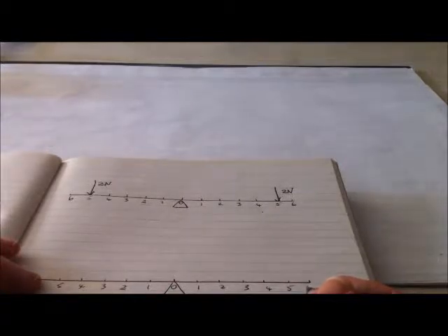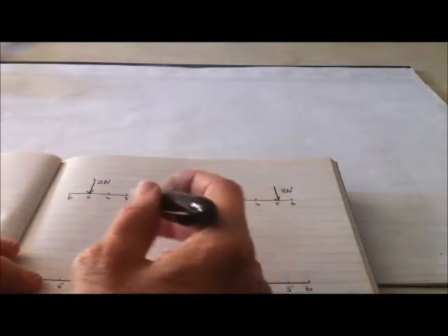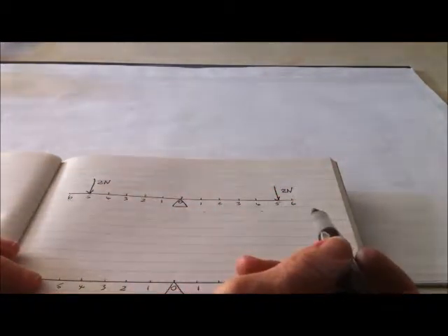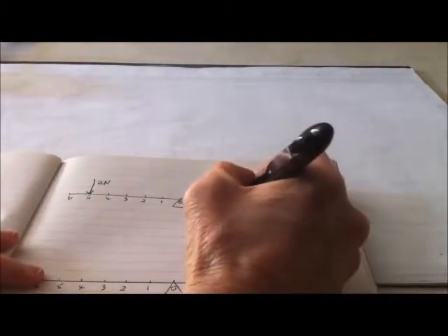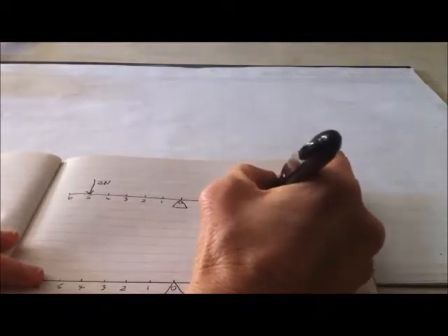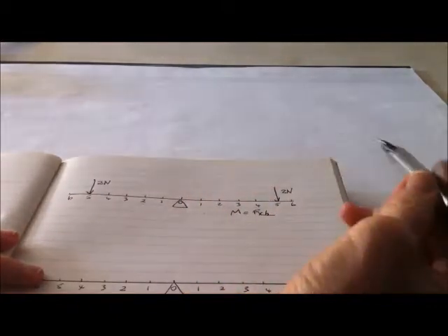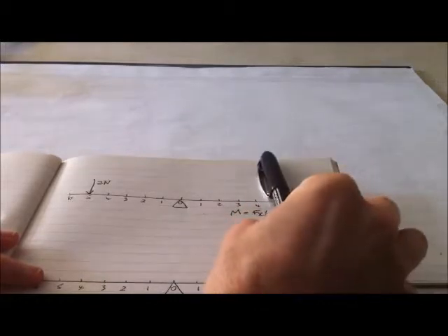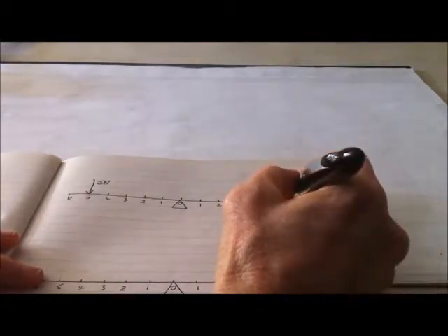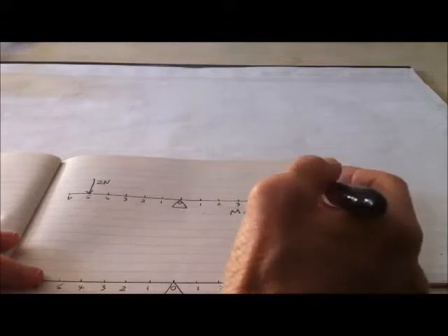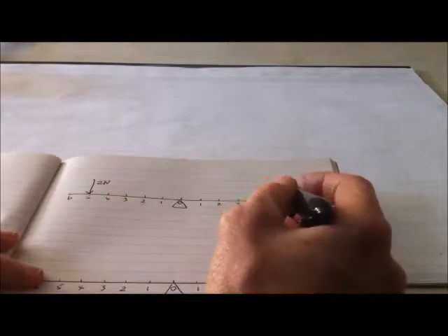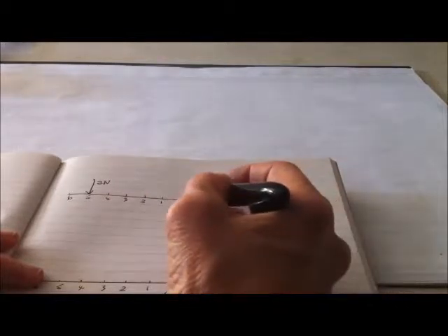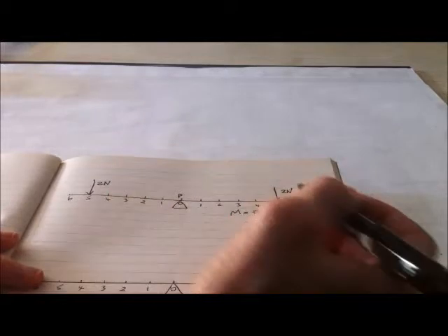You can probably see intuitively that because the beam is balanced at the centre point, both of these moments are going to cancel each other out, but let's just show that mathematically. We know that the moment is always the force times the perpendicular distance. You look at the line of action of the force, and to find the perpendicular distance, you take a line that is perpendicular to the line of action and goes back to the pivot point. We'll call that point P, the pivot point.